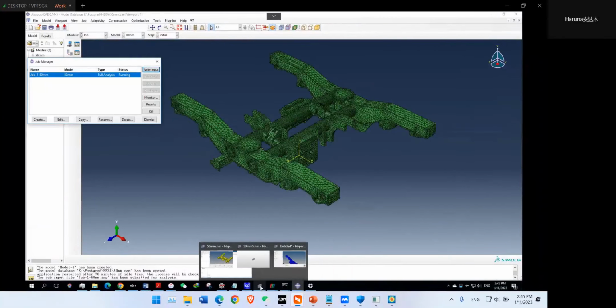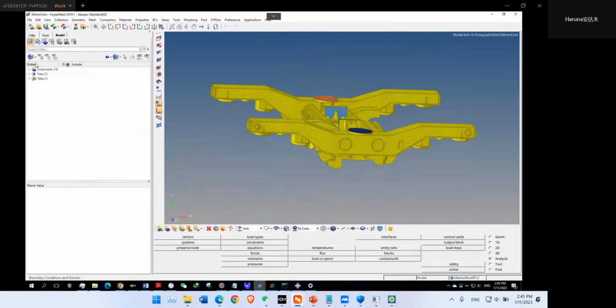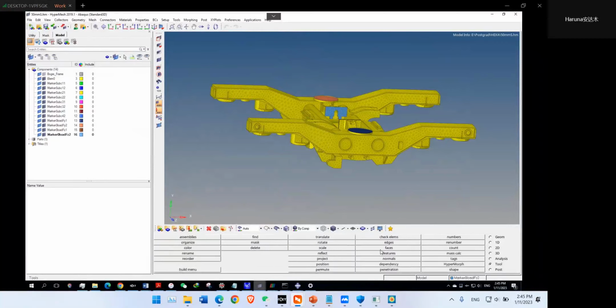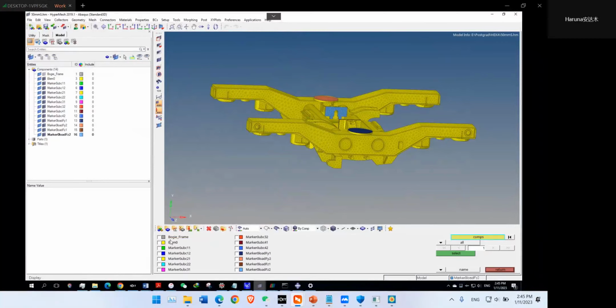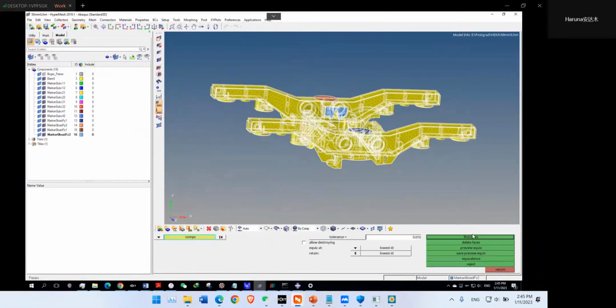So meanwhile, while this is running, let me show you how we do it for our SFEM. Unlike that of the FEM, you have to create some markers. The way to do this is to create a face, like it's going to be a 2D mesh around it. The way to do it is to come to tools, faces, and select element 0, which is our 3D mesh. So select it and find faces.